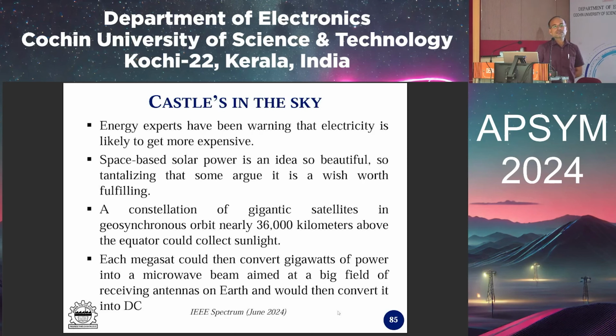Maybe we'll try to include that too, sir. And for those measurements, we understood that the larger the fabricated prototype, the better the performance. For the antenna, the FSS area should be twice the antenna illumination area, so that we get better performance.